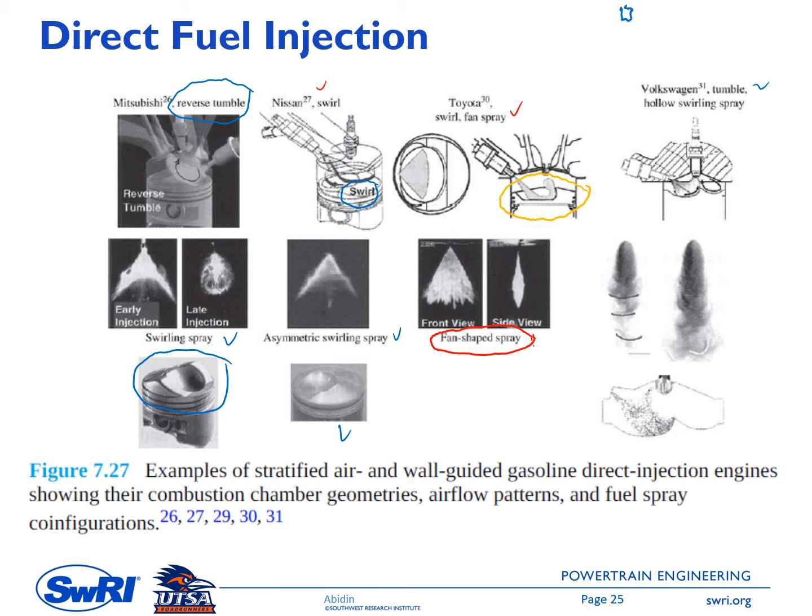So the solid spray, usually we have this spray, which means here all is the fuel spray. And then for the hollow spray, we can have it like this. Okay, so it means in the middle here we don't have a spray, so it's a void zone there.